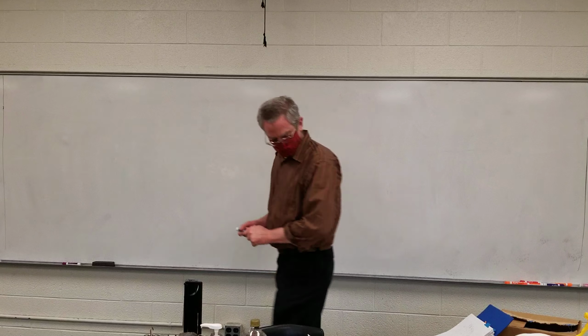So for the resistor, it's just 15 ohms. For the inductor, it is J times X of L, so 16.965 ohms. And this would be negative J X of C, so 13.263.